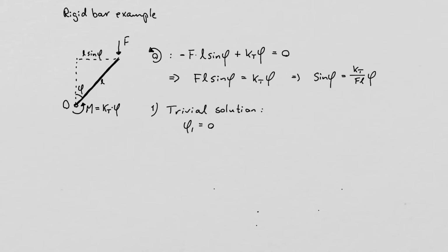Possibly a little bit surprising, because we do know, at least also from the elastic beam example, that at one point the beam will buckle. However, the straight equilibrium position is always a solution. The case is then it just becomes unstable if we also have another solution. But let's see, what about the other solution? We will, of course, call that the non-trivial solution, but also refer to that as buckling. This is an actual buckling case, right? So what is the condition for buckling?